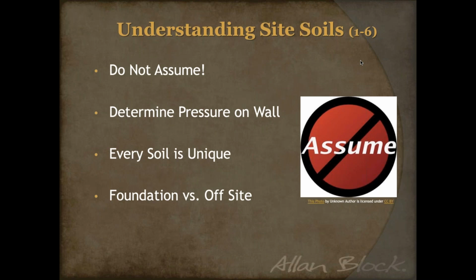So designing any walls using poor foundation soils can lead to huge failures. And that's why it's so important not to assume, and make sure that the soils that are on the site are either suitable for the design of the wall or to put as the infill. And if they're not, it's important to know when we need off-site soils.